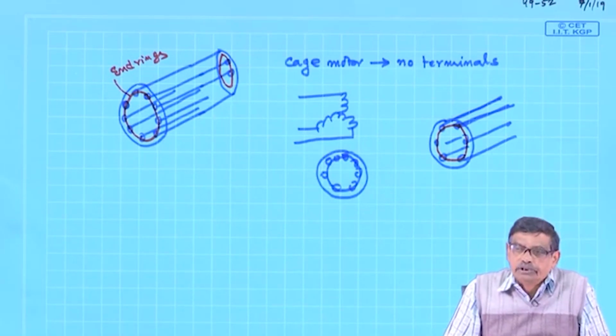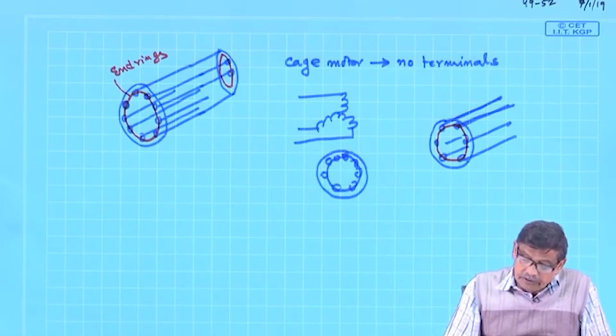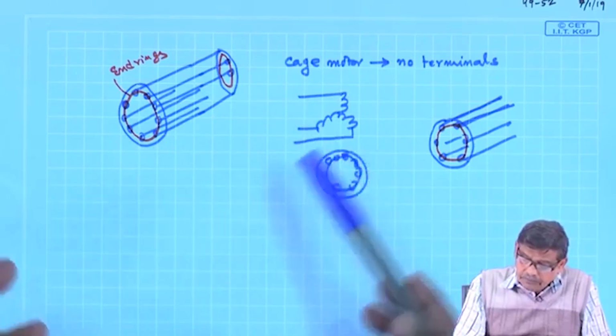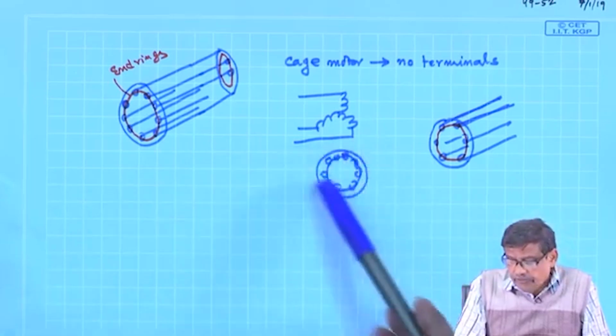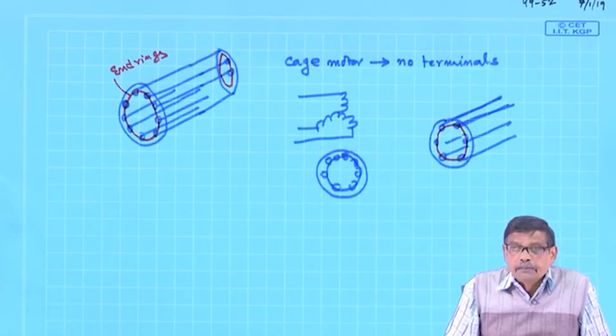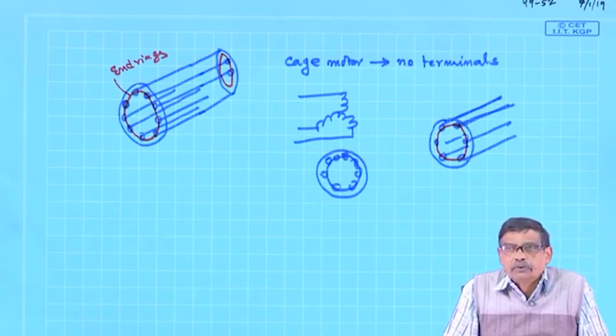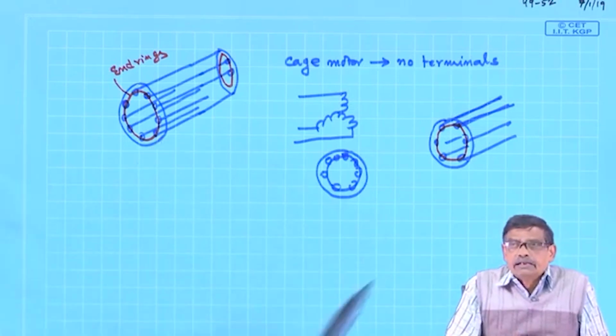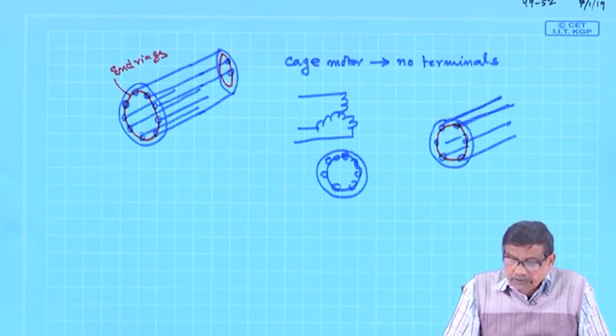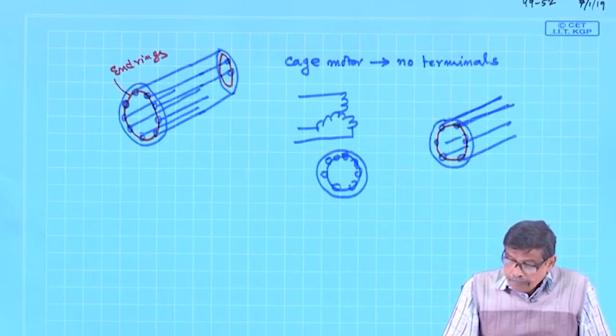That is the most crucial point, because the stator does not know what kind of polyphase winding the rotor has. It is only interested to know whether it is developing the same number of poles or not. Based on that, the stator draws extra current from the supply when rotor current flows.